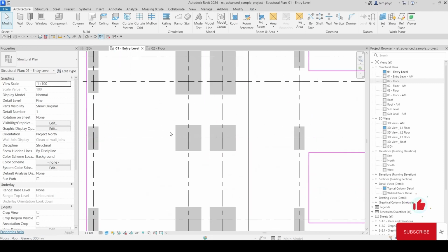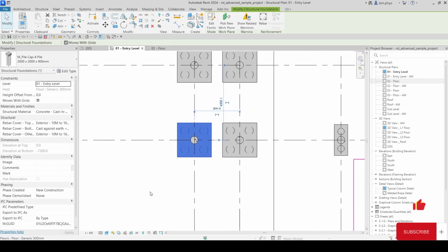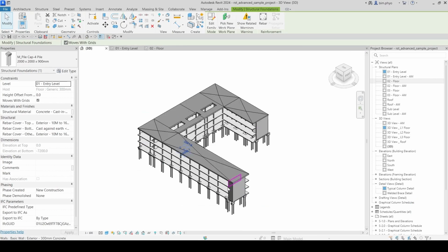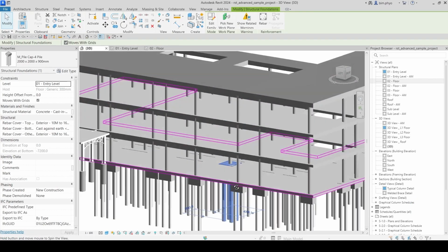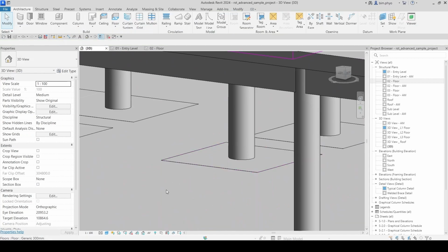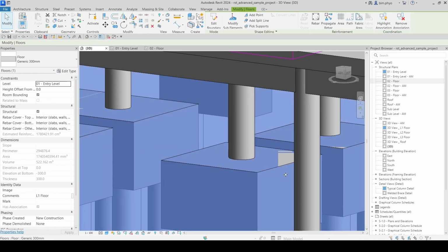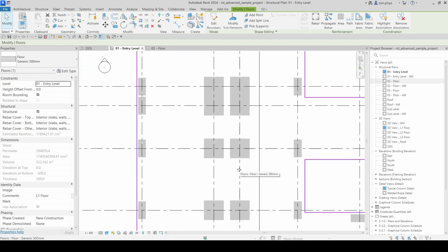Okay, how about this, the pile cut? And look at this. Okay, I was going to see inside the 3D view. You look at this. The floor is this. He cut to this one. In the drawing, we cannot show the dotted line because the floor surface and the pile cut surface are the same level. It must be the solid line in your drawing presentation.